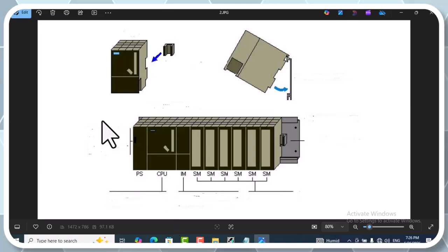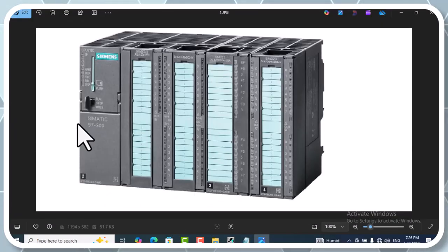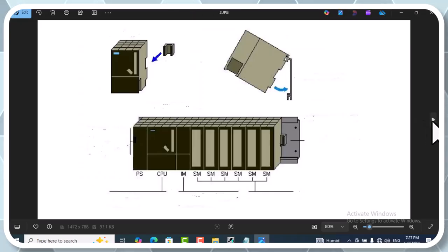And also, my friends, let's look at the biggest advantages of the S7-300, which is applicable for another series of Siemens PLC. It has natural cooling, and no cooling fans are required. An expansion module can be added when the system grows. The mode selection switch lets you switch between stop, run and other programming operating modes.